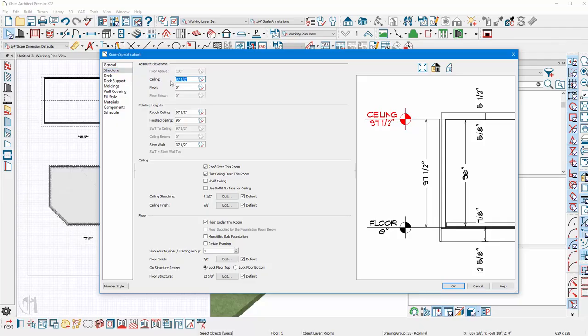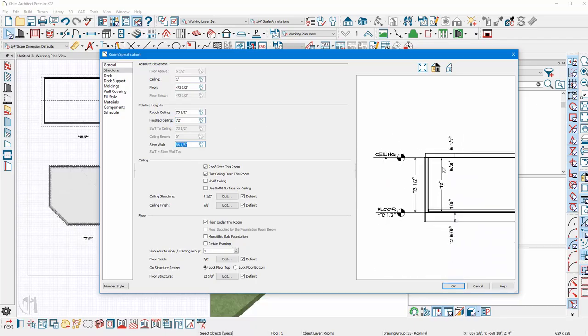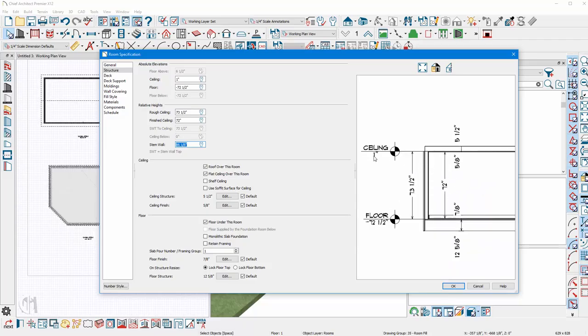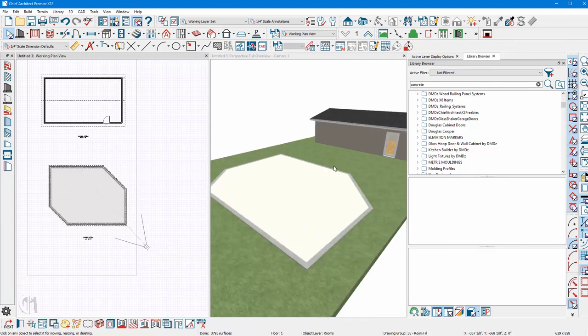So since we made the ground at -1 to the 0 point of the lot, I'm going to say 1 just to keep it up for now. And then going down here to finish ceiling, I still want it a good 72 inches deep. And you might have to rearrange your little diagram to see what's going on. But basically, again, now my ceiling's at 1 inch, my floor is 72 below 1. Okay, click OK, and it drops it right back in there, which is really nice.